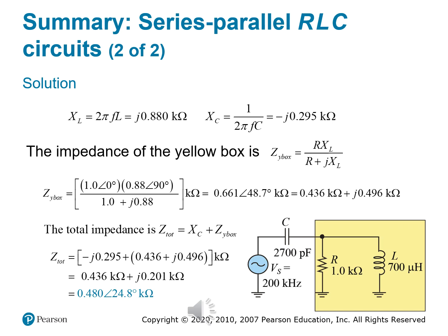and that same inductor. So let's plug and chug. Plug this into the formula for the impedance of the parallel elements, where you have the impedance of the box, Z box, equal to R times X of L divided by R plus j X of L.